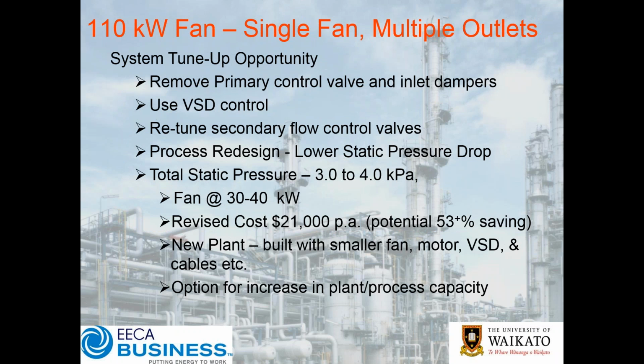Well, when we looked at the system and had a closer look and started to tune and figure out what we could do, by removing those additional control valves and reverting to VSD control, we dropped the total static pressure, actually quite substantially to under 4,000 pascals, because what we found we could also do was reduce the pressure drop across the actual process by getting the flow right, by not disturbing the flow upstream of those outlets. You'll recall a few slides ago we talked about how whenever we have these dampers they can disturb the flow and cause downstream effects.